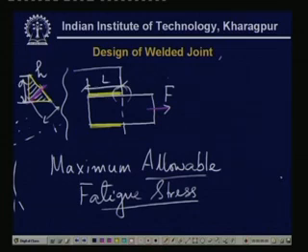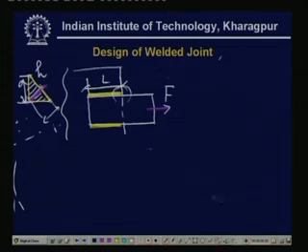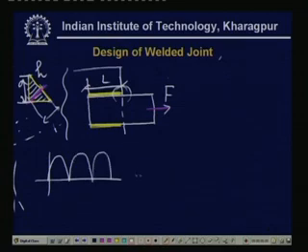Those are again tabulated, but there are various techniques in various countries. For example, in the United States, the maximum stresses are tabulated in this form. First we calculate the maximum allowable stress for repeated loading, that is the loading of this type, where the minimum value, F minimum, will be here, and that is equal to 0.